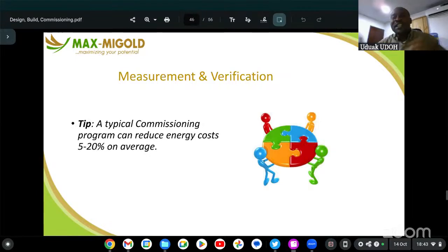For instance, they install an AC, right? And you see that the compressor was not picking, or probably the AVR surge protection unit that was installed with it was not properly installed. They tried testing. There could be some surge voltage fluctuation. Before you know it, it affects the compressor. You have not just wasted energy on testing. I'm not getting the required cooling effect. What is happening? The compressor is not picking. It's a new AC. What's happening? You're burning energy, your consumption is going up, until after much testing, the compressor went bad.